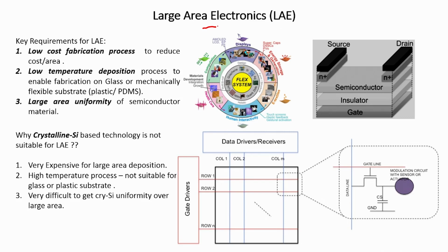So let us consider a display screen. Now if I have to build transistors etc. on a substrate that is as large as a display screen, for example a display screen is several inches to even several feet in length, and if we need to build all the semiconductors and electronic devices that are present on the screen using crystalline silicon, one would require either a large tile of these crystalline materials, or one would require a very large wafer, and both these are going to be quite expensive, and it is probably not the best way to go about building such a large area system.